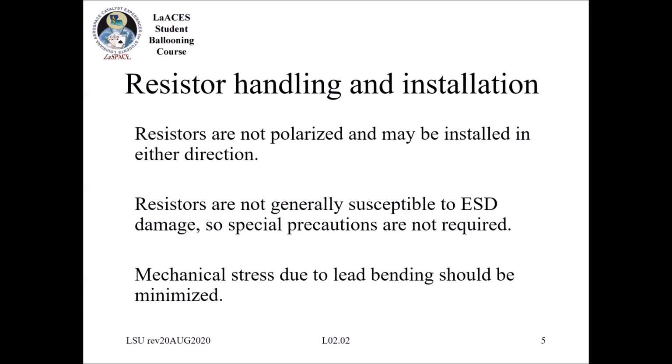Okay, so resistor handling and installation. Resistors are not polarized, meaning that you can put them in any orientation, and they may be installed in either direction. They are generally not susceptible to ESD, or electrostatic discharge. That's what ESD stands for when you see it. So special precautions are not really required.